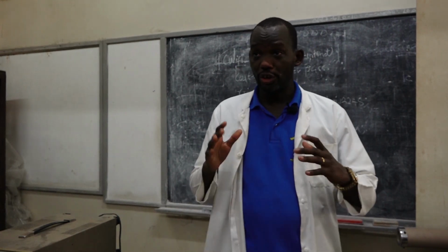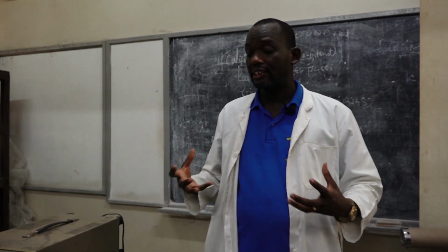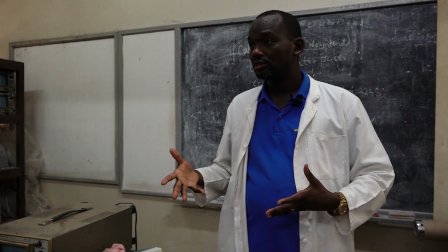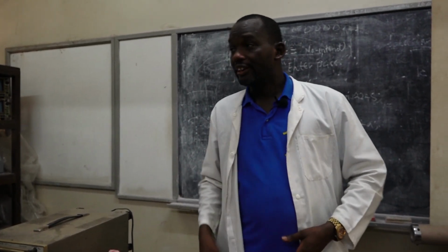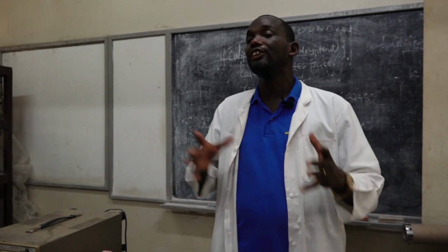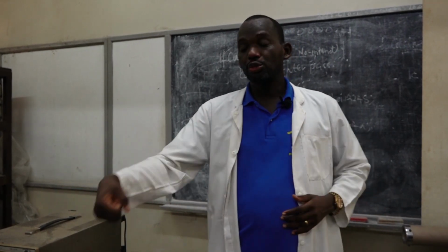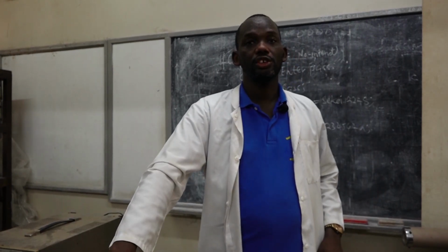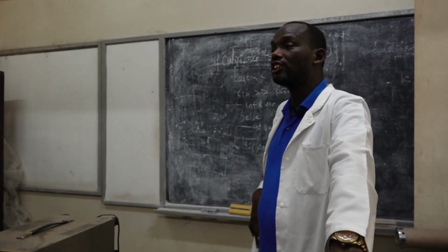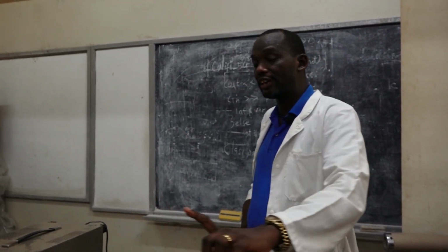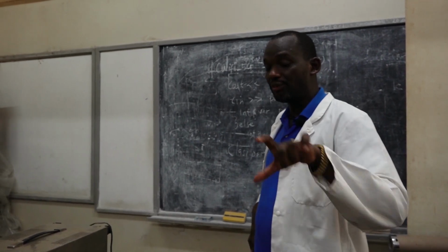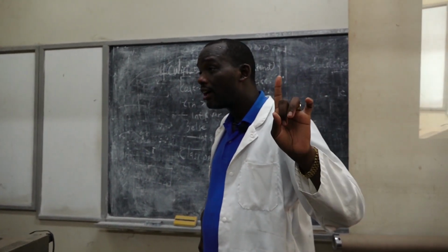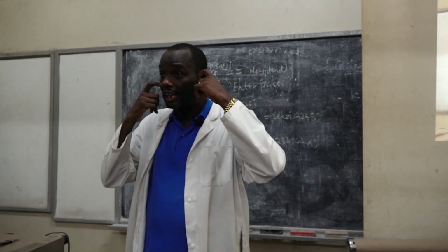Class, listen. Now we are going to the task, the third part. Now we are going to start on the waveforms we have discussed in theory and in simulation. Are we together, class? The first waveform is the input from the main AC source. This oscilloscope can withstand even that 220 volt, but you need special connectors in order to connect this oscilloscope to the domestic power source. Because we don't have those connectors, we cannot measure or study the nature of the waveform of the AC mains at that voltage. Is it clear or not clear?